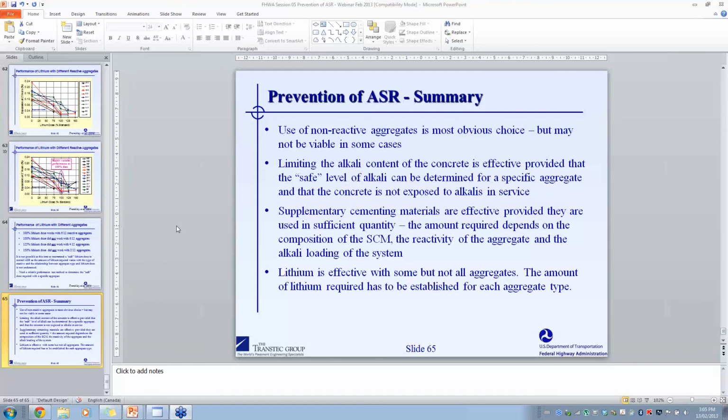They may require 4 or 5 pounds per cubic yard. But a lot of this is sort of empirically based. I'd be very hard pressed to put a scientific relationship to that. But it certainly seems like the more reactive forms of silica, like the opaline silica, maybe the volcanic glasses, would react at a lower alkali content than microcrystalline or strained quartz. But beyond that, it's difficult to establish a very firm relationship.